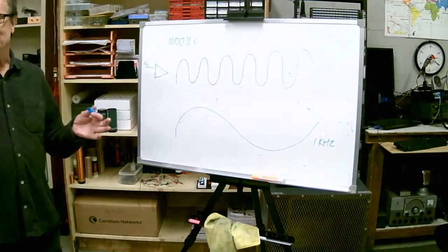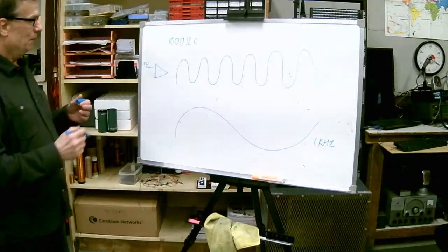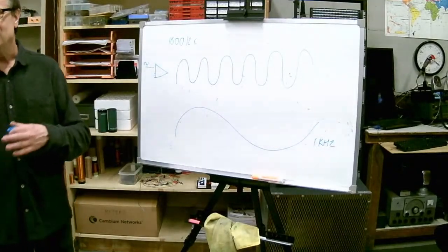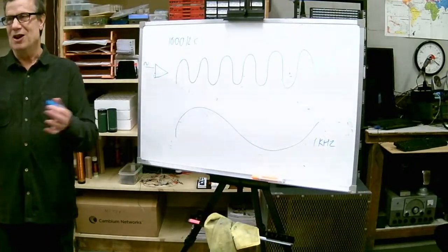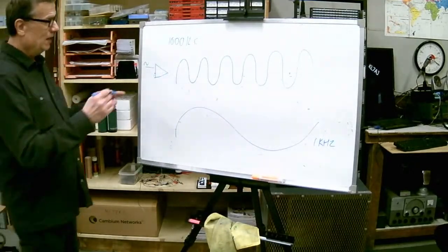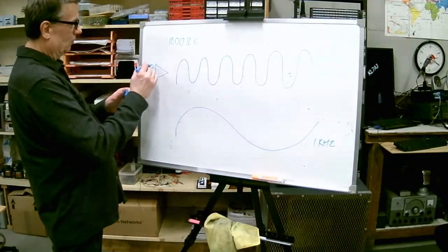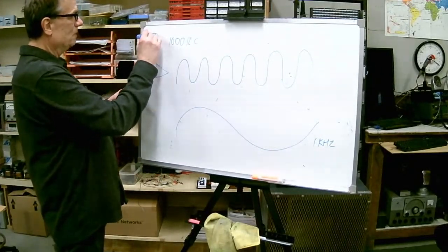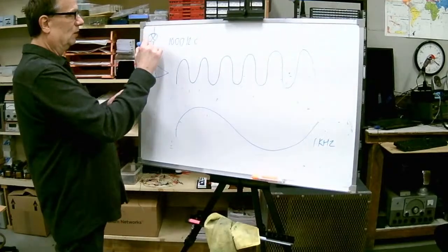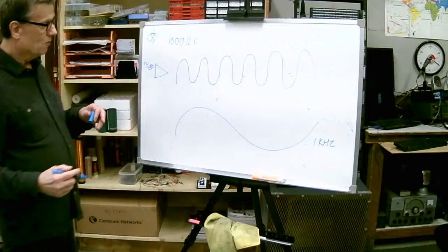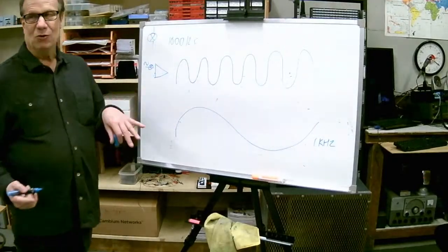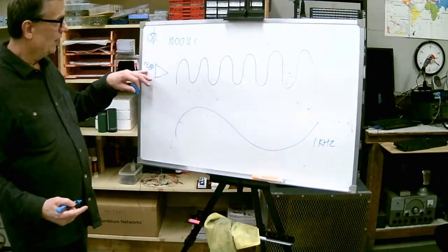A diode can do it. There's more elegant ways of doing it, but any nonlinear device, in other words, any device that does not follow Ohm's law strictly, where the voltage and current are not exactly proportional, you can get differences between it. So this is a general symbol for a mixer. And just like we use it for down converting our radio frequencies to IF frequency, same thing will allow us to modulate this amplitude with this.